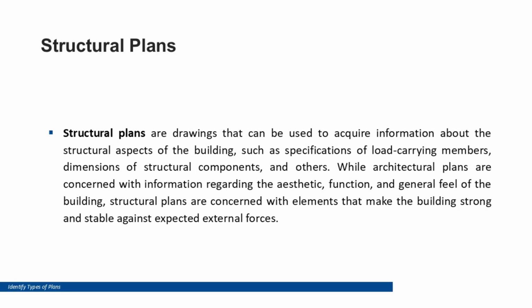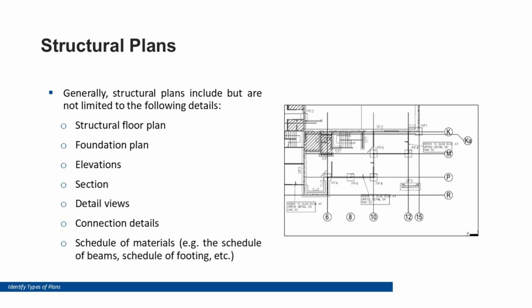Structural plans. Structural drawings show the engineered elements that give the building its strength and stability. These include footing and slab plans, beam and column layouts, reinforcement detailing, retaining walls, bracing and tie-down systems. These drawings specify depths, diameters, bar spacing, load-bearing capacities, and structural material requirements.